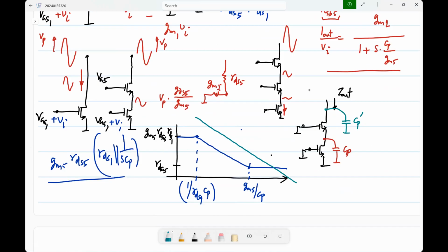Smaller one. And if you want the series, if you want, let's say, two impedances again plotted on a log-log scale, and if you want the series combination, what will you do? Plot the higher one. That's all. Okay. So this is always the case.